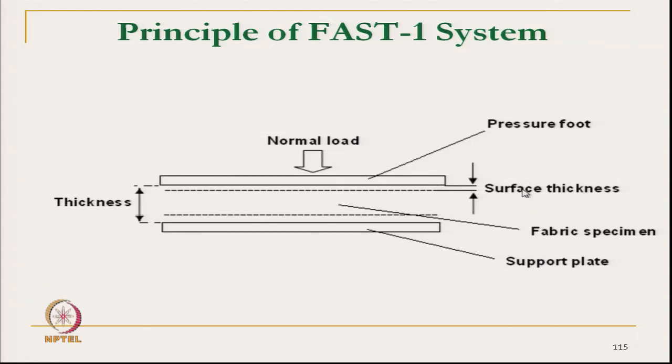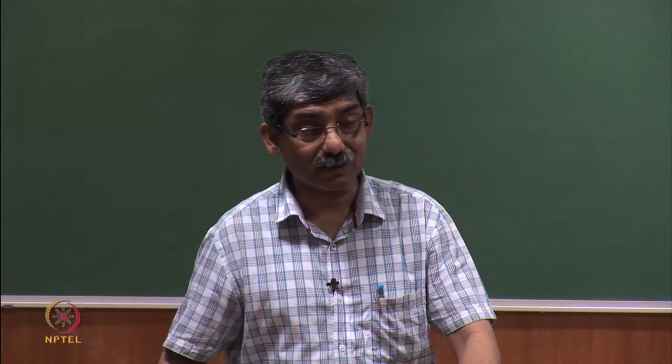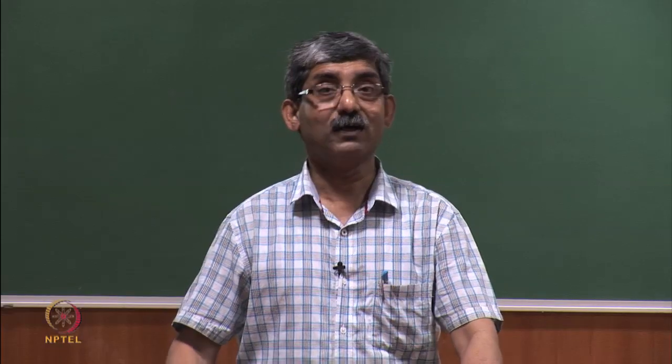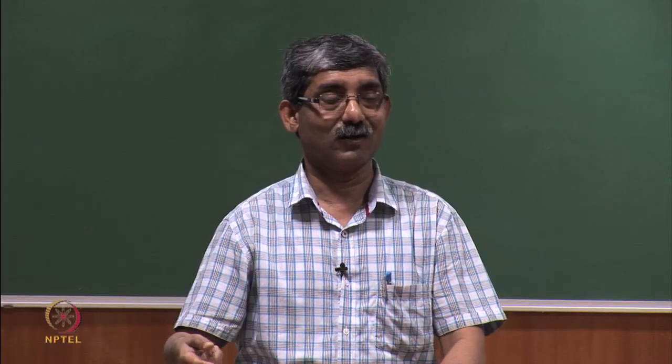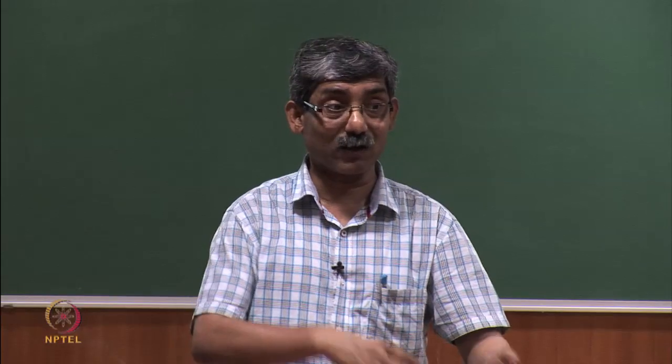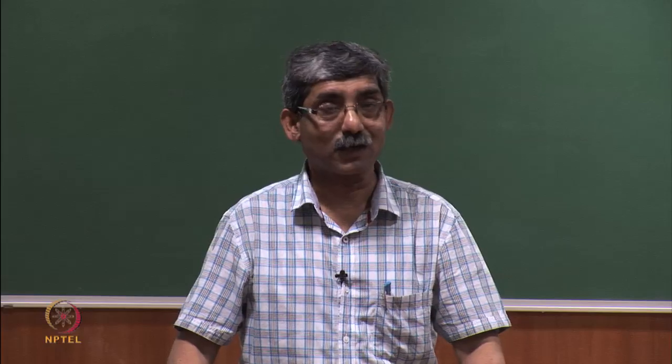This difference is the surface thickness. And if we wash the fabric, we may get a higher surface thickness. That is called released surface thickness. So, from here we can get an idea about the hairs present at the surface, and also whether the finishes we have applied are actually working or whether the finish has been washed away. That information we can also get from released surface thickness.